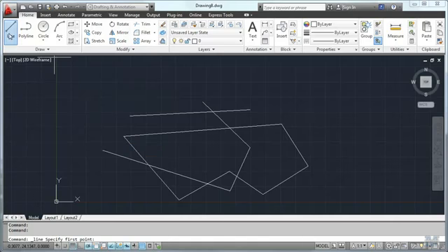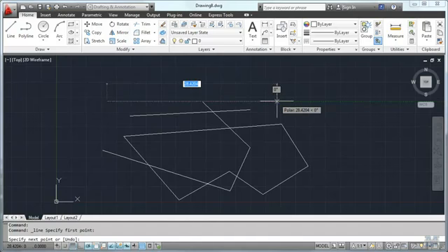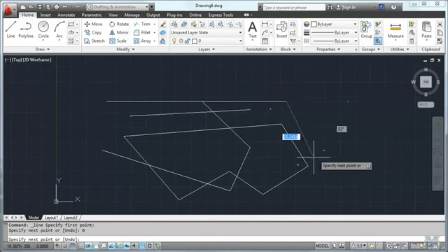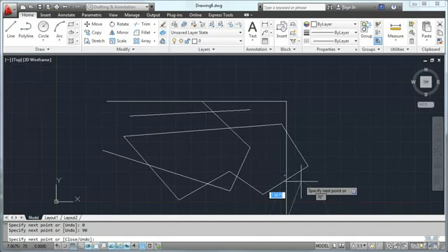The way we've been drawing with the line tool, notice that when I first clicked it was at 0. When I move away it goes a certain distance, so if I want to go 30 units across, I can type on the keyboard 30 units, hit the tab key to the angle, and I'll just use it as 0, hit enter, and it draws the line for me. And if I wanted to go square down another 20 units, tab key 90 degrees in this case, and hit enter, I can do that. Now I'm off the screen.